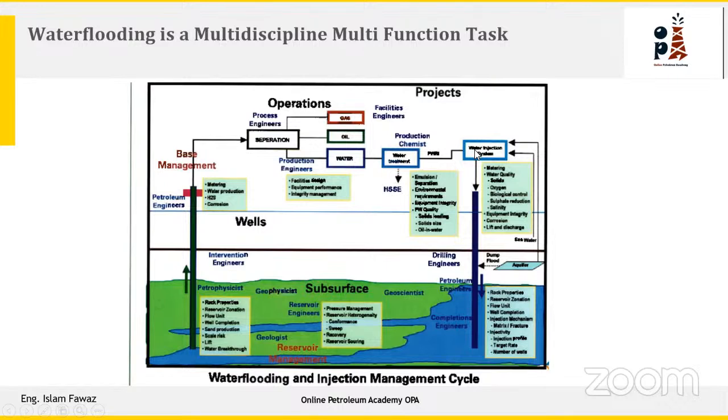After that, the water is injected back to the reservoir. So you have to make sure the injected water is very clear, because if we have unclear water, the unclear water may block the perforation, and your water flood project will end up in vain, and you will lose the injection into your reservoir. So I would like to mention the main message from this slide: don't work in your island, because everything is communicated, and share your knowledge with your team in order to maximize the benefit from the water flooding project.